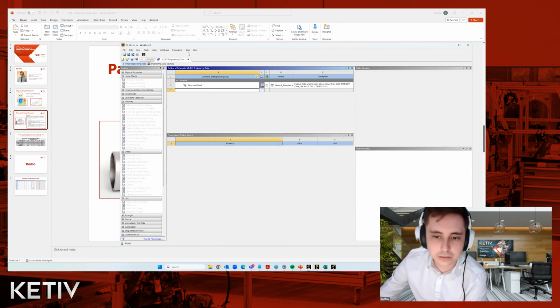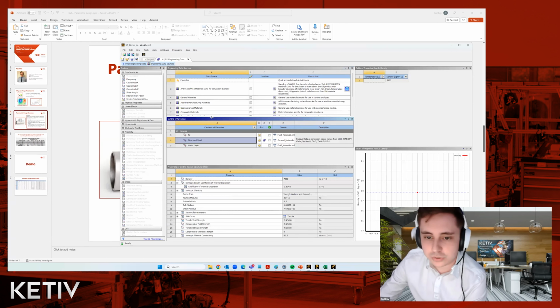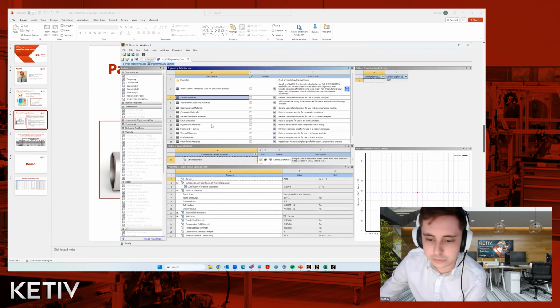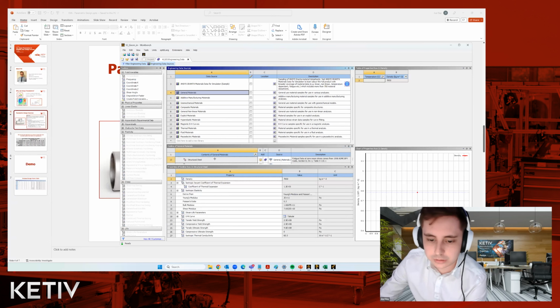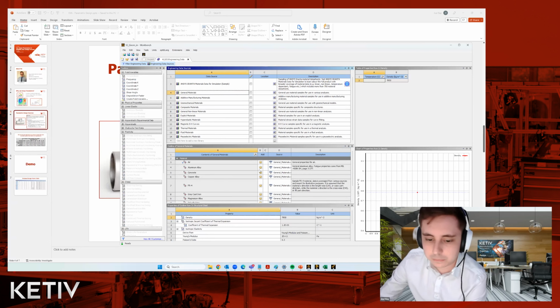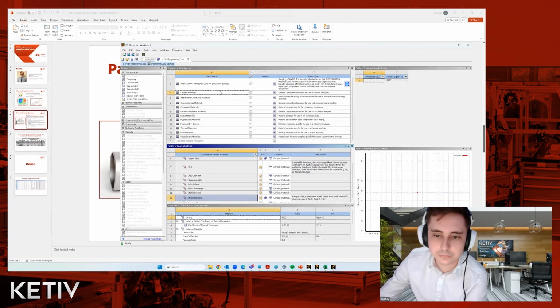So to add material properties in engineering data, it's very easy. You just go to this engineering data sources, and of course you can add your own. And I won't go into too much detail on that. But I will just add the materials that we need: aluminum alloy, copper, and then we'll go to Granta.